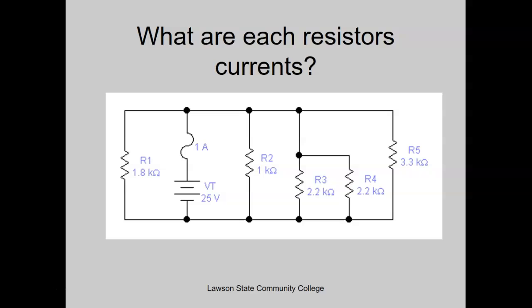What you're looking at is a schematic. Just like resistors don't look like these, fuses don't look like two half moons facing each other. But it does represent what a fuse does, because a fuse is a little piece of wire that's just about nothing, that breaks at the drop of a hat if you get too much current moving.